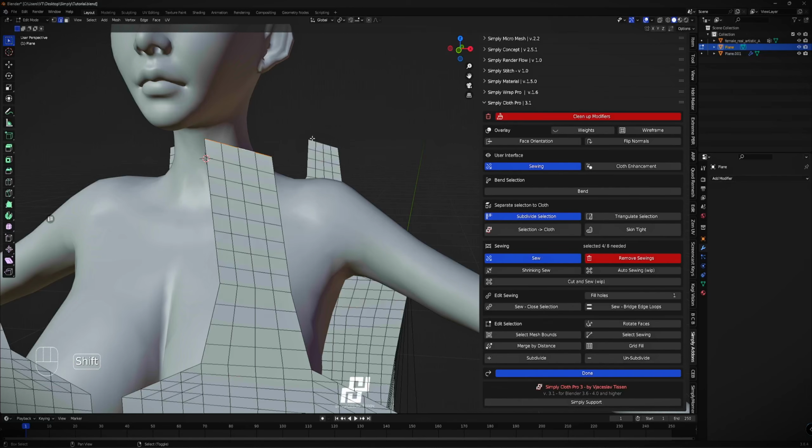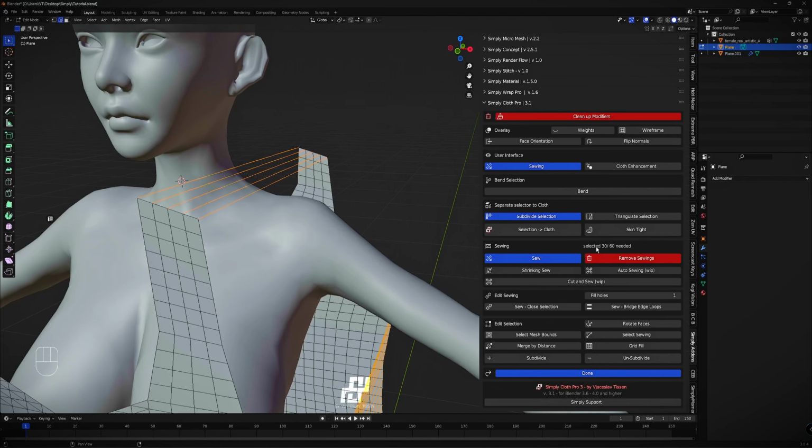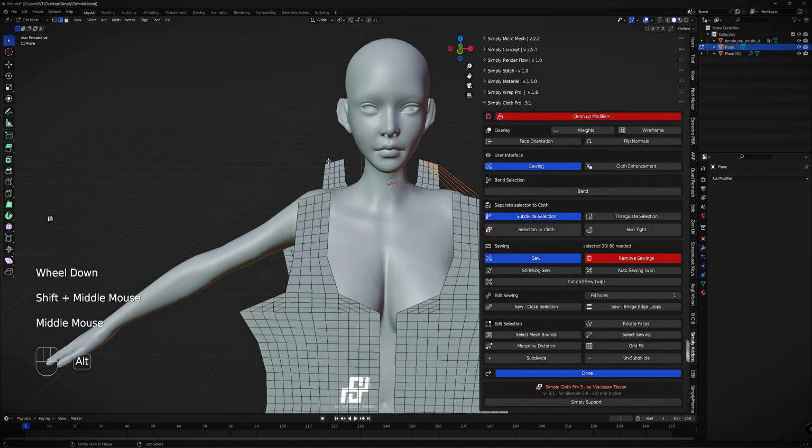Sometimes people make this mistake, and we have 7, and then we have bad sewing. But if we see it here, 8 selected, now it's correct. If we select this, we have 4 selected, but we need 8. And when we select this here and have the 8, we can easily sew them. So we have a small hint how to sew them correctly.